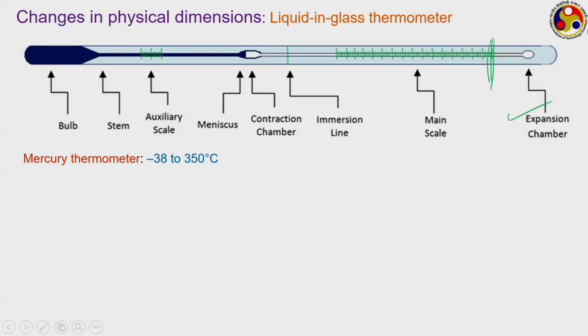applications. We can lower this freezing temperature a bit if we use a mercury thallium mixture, then it goes to -56 degrees Celsius, which can be sufficient if we are looking for, say, weather temperature measurement in the toughest of conditions, but if we are looking for certain kinds of cryogenic applications etc., this is still quite high.